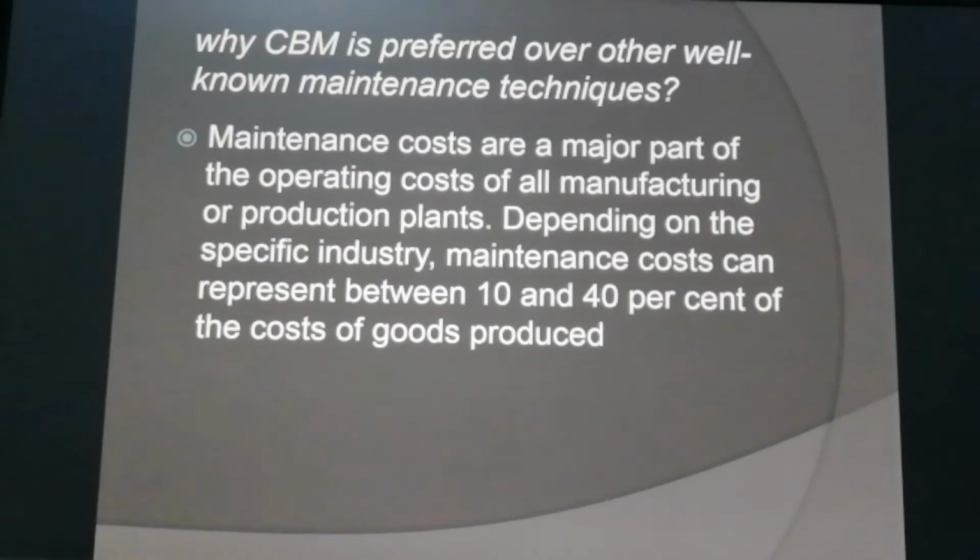Okay, why is CBM preferred over other well-known maintenance techniques? Maintenance costs. Maintenance costs are a major part of the operating cost of all manufacturing or production plants. Depending on the specific industry, maintenance costs can represent between 10 and 40% of the cost of goods produced. So it is important to decrease the cost and increase productivity. So CBM is considered the best technique.